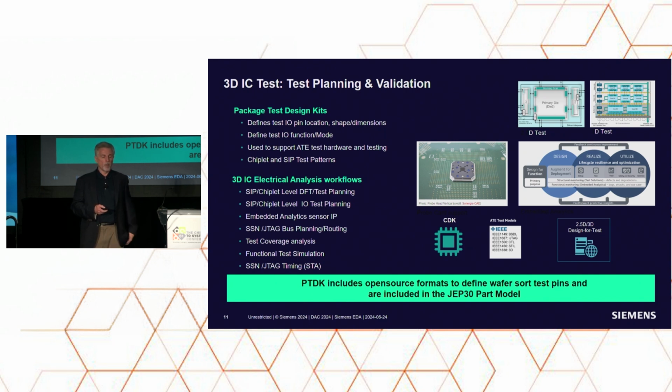They're not even packaged up. So that information needs to be included in these mechanical views as well as the electrical views. So in test mode XYZ, these are the pins that are applicable. And that information is then used to build the hardware testware. So it would be the probe cards and the test hardware. So they're the consumers who would use that type of information.